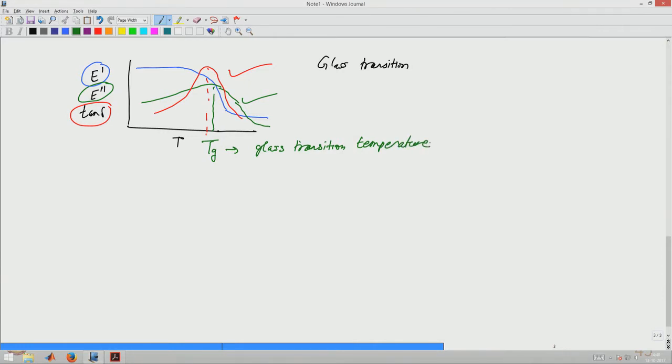In the design of polymeric systems, it is very important to know the behavior of the material and where the glass transition is with respect to the performance temperature. In the case of rubber-like materials, we have to make sure that the material is used at temperatures much higher than the glass transition temperature, so that the rigid or brittle response expected in the glassy region can